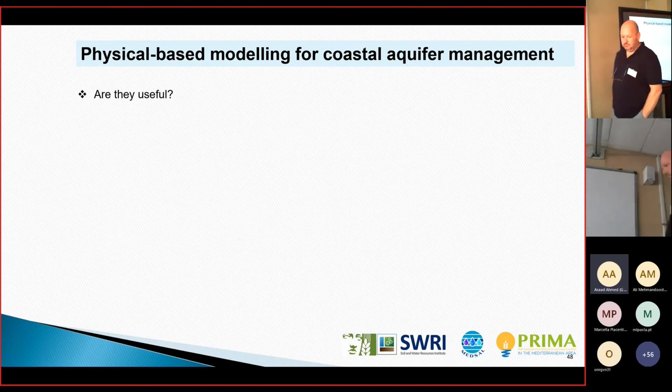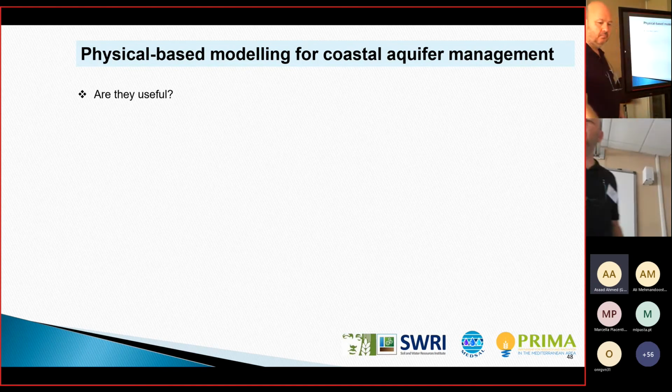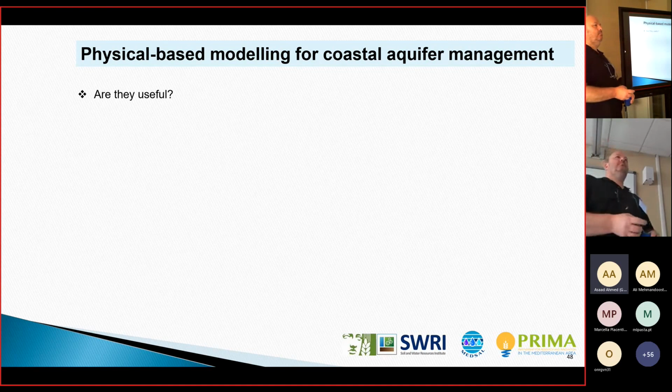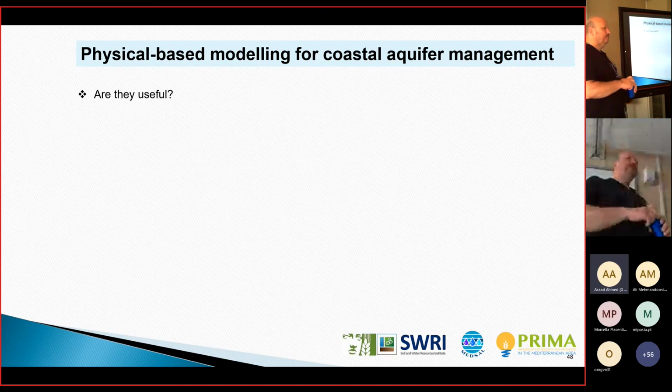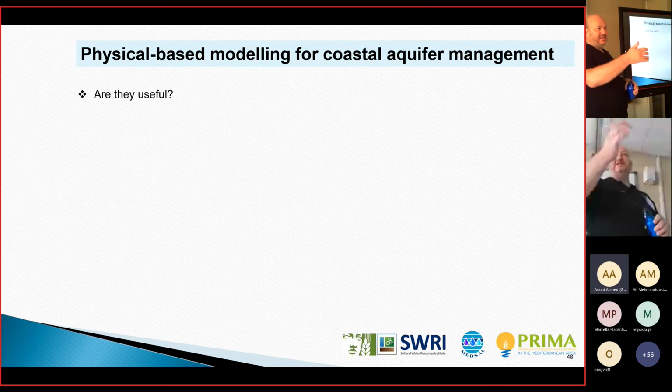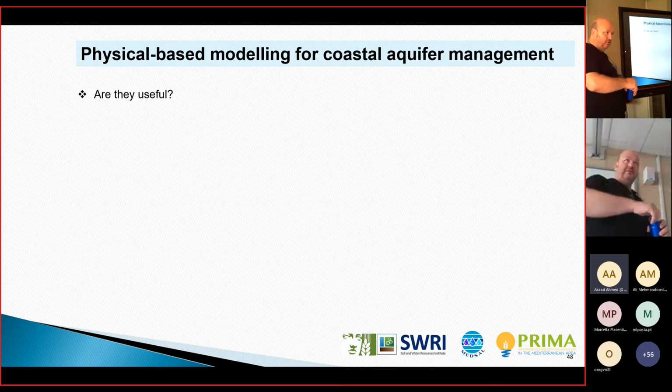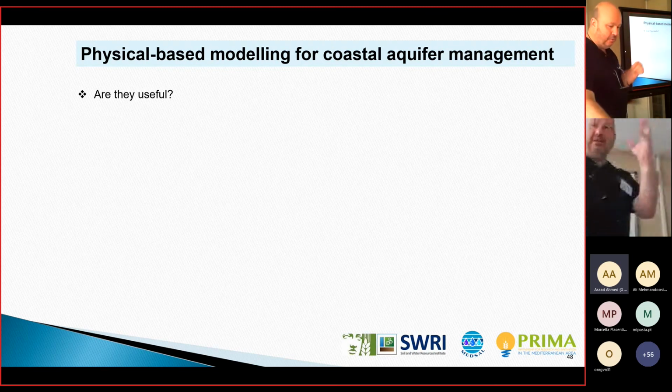For instance, it will allocate injection wells for managed aquifer recharge in order to help control the freshwater-seawater interface. However, I wasn't able to apply the SWI tool in the model because it's a regional scale. So a quick answer is that we need it, but we should be careful.